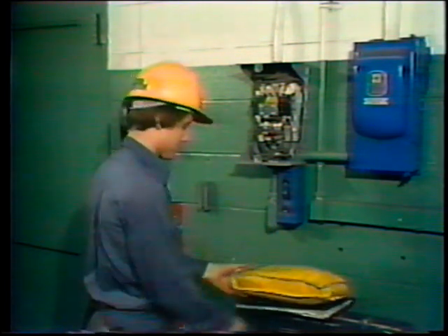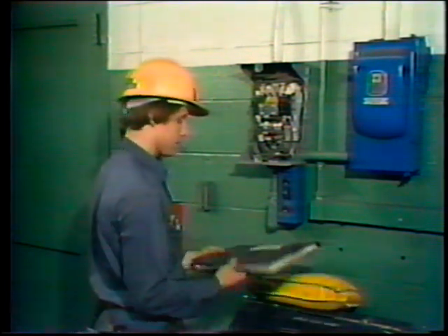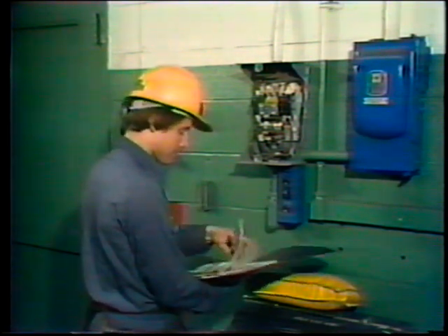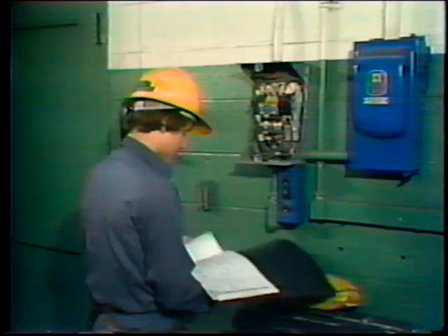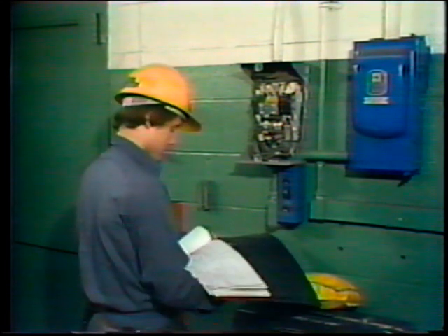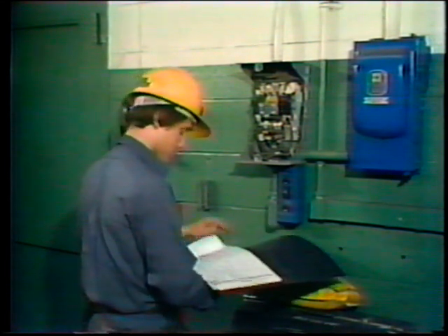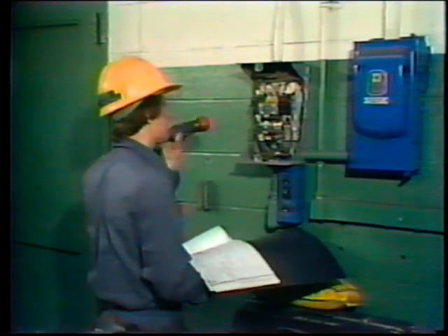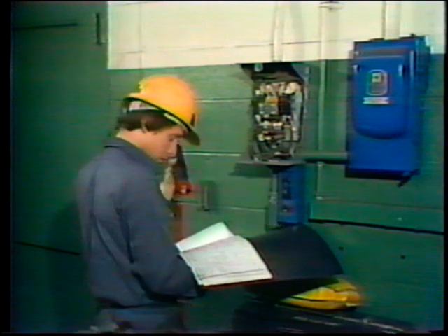Next, the electrician uses the motor controller's wiring diagram to find the components in the actual controller. The easiest way to locate the maintaining contact and the wires leading to it is to first locate the magnetic contactor's operating coil on the wiring diagram. The operating coil is a good reference point from which to find the magnetic contactor in the actual controller.